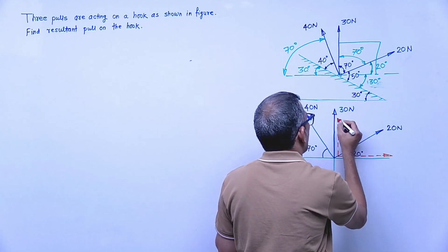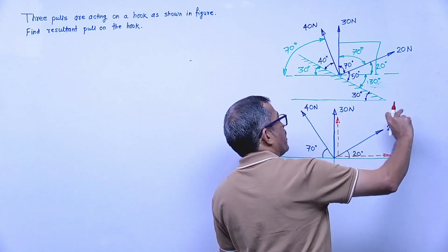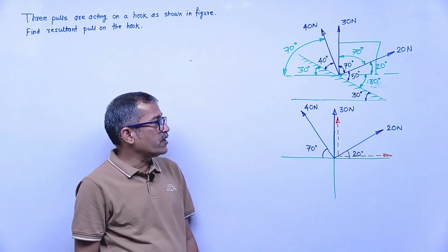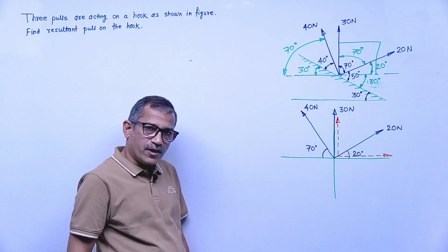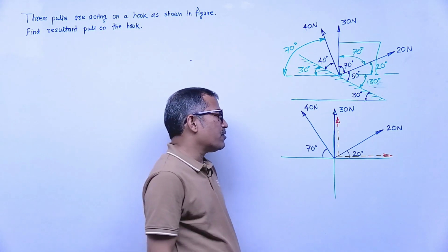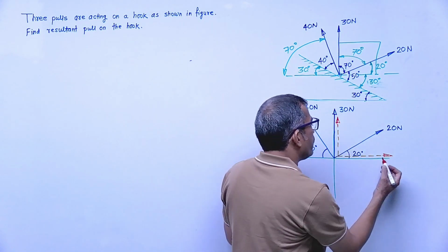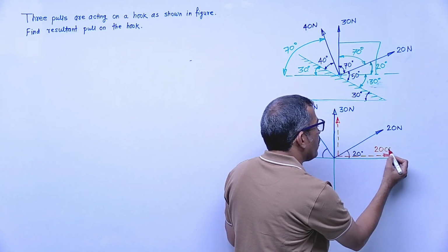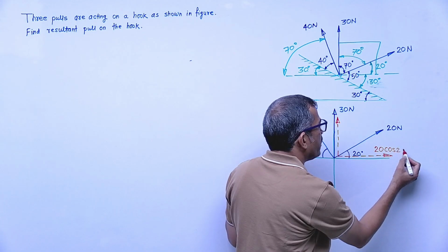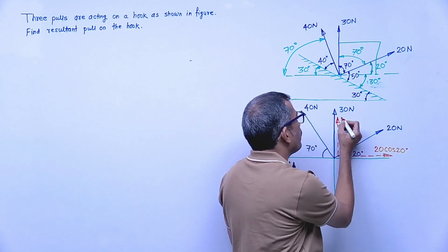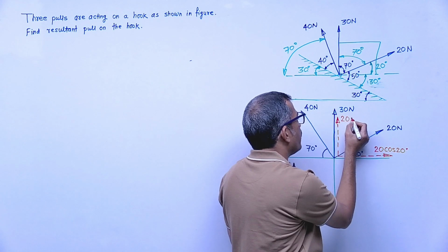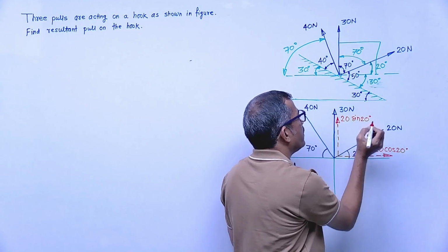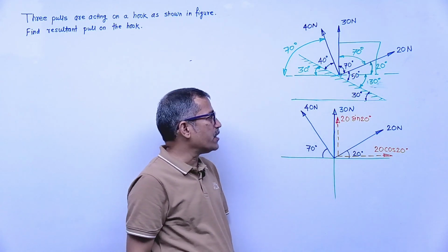Nature of force is away. Away, pull type. Components must be away, pull type, pull in nature. Which component is cos? Angle is given with what? Horizontal. The horizontal component is 20 cos 20 degrees and the vertical component becomes what? Sine component, 20 sine 20 degrees. Clear? First resolution clear.